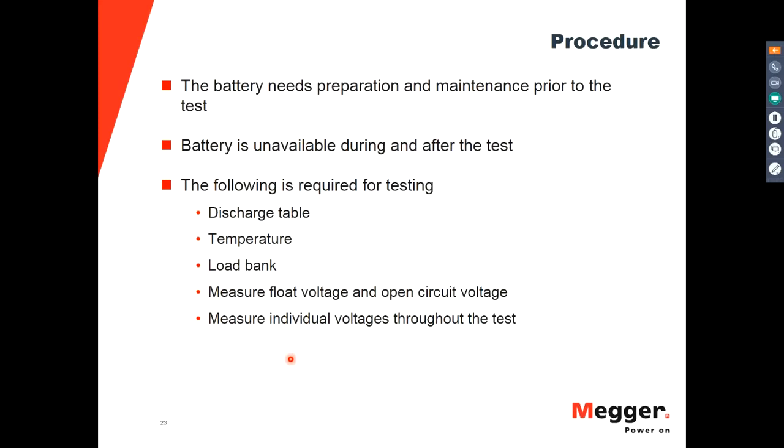The other thing that you need to consider as part of your procedure is that the battery is going to be unavailable during and after the test for a certain amount of time. And this unavailability might affect the resources or the time that you have available for the test, and might also require some backup for your battery or for your facility, for your substation.